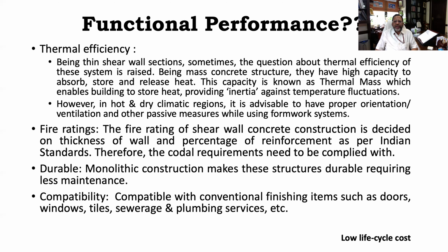Suppose you are doing it for a residential building and you are making a dwelling unit, a fire rating of at least 1 to 1.5 hours is required. So for that 1 or 1.5 hour rating, if you are having a 100 mm wall, what is the reinforcement requirement that needs to be complied with? Using those prescriptive codal requirements, you can achieve the desired fire rating. And being monolithic construction, absolutely there is no problem.